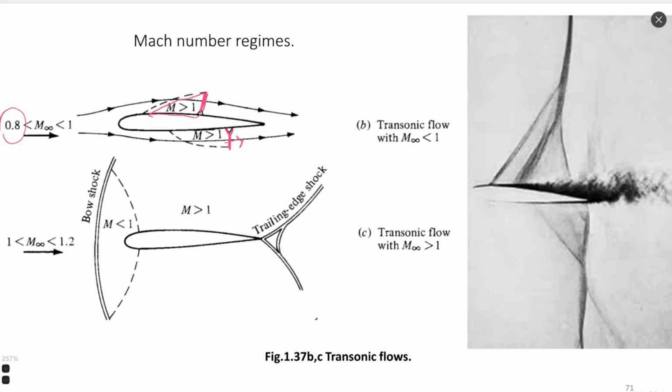We have supersonic flow from Mach 1 to Mach 1.2 approximately. And near the airfoil such a bubble of subsonic flow is created. This bubble will be discussed widely in gas dynamics, why it appears. Just anticipating, I tell you that it appears because there is a reaction of the body on the flow, and when the flow impacts the body it generates pressure waves, and these pressure waves accumulate.